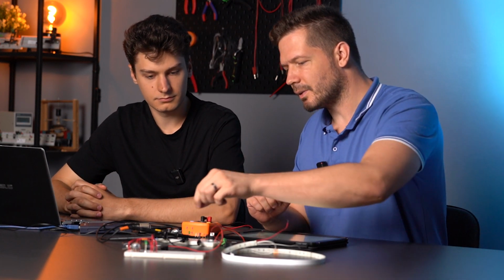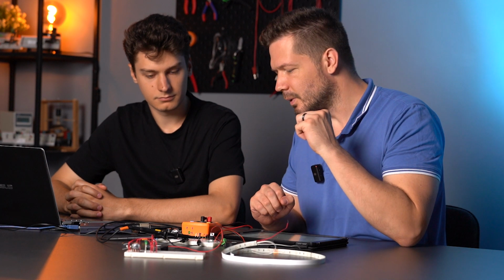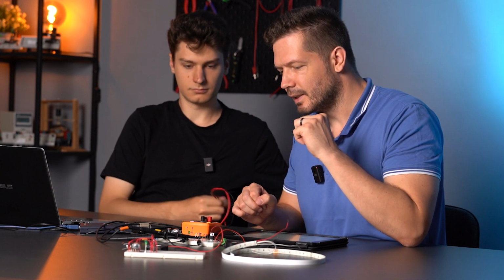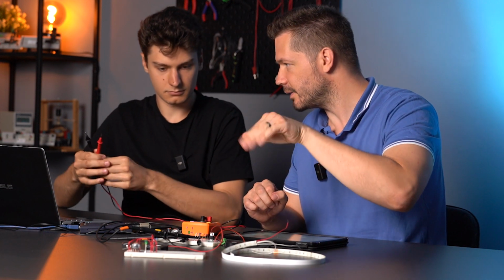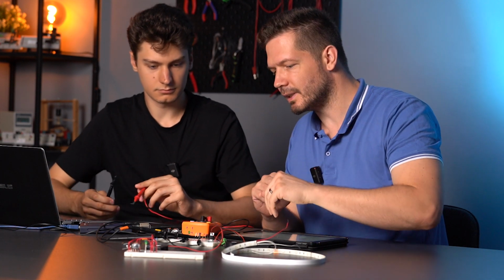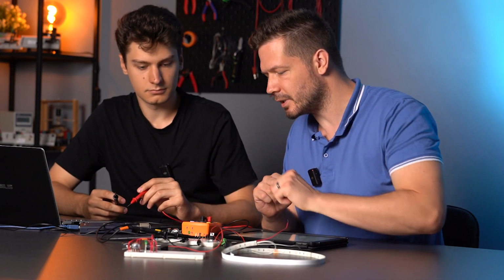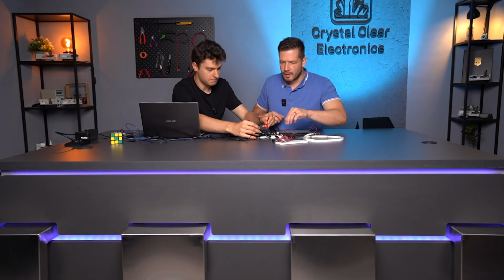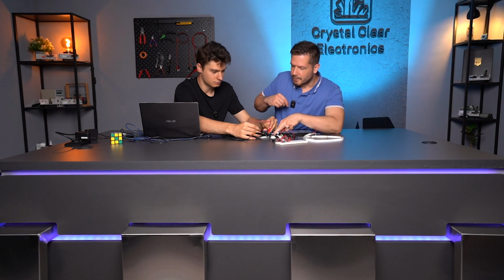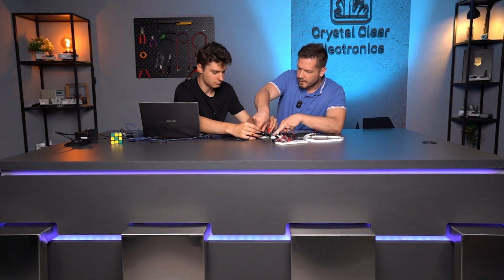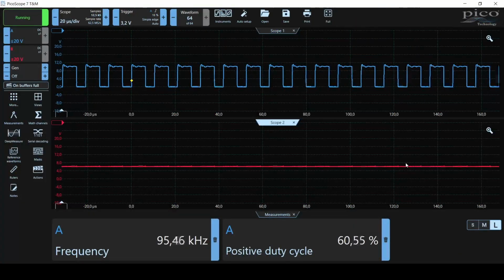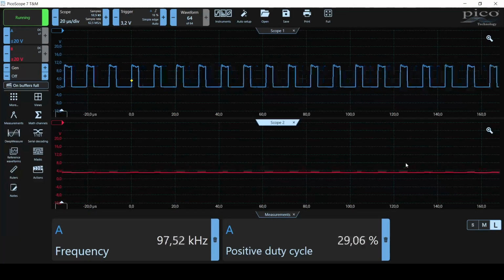Let's see what happens when we measure the voltage on the series connected LED and resistor with a multimeter. Here, we know that the LED and the resistor are not capacitors, so the voltage really jumps between 0 and close to 12. I will place it there then. Let's see how a multimeter behaves in such a case, when it is actually measuring a pulsating voltage. You can see that as I change the duty cycle, the measured voltage